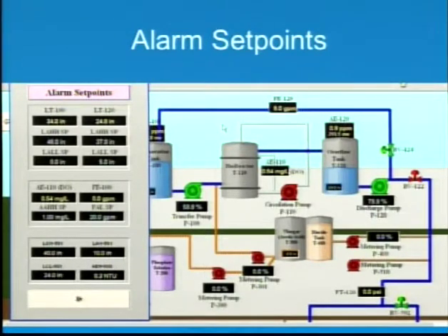But for example, in this case, the set point is not to exceed 1 part per million nitrate N. Also in this scenario, if I can ever find my arrow, at the lower left-hand side, you see the turbidity as 0.3 NTU. And if you're exceeding that turbidity, it's not going to allow water to leave the system.